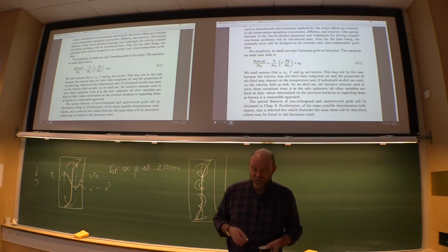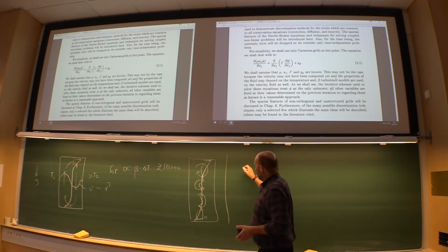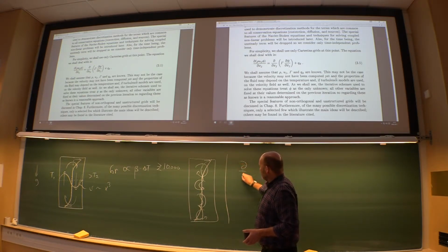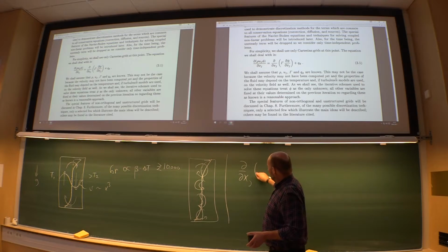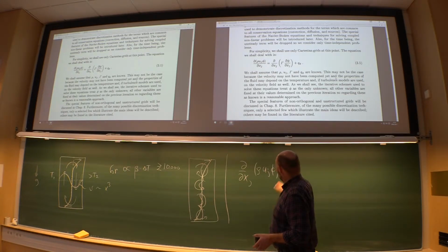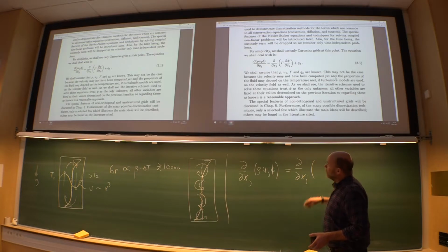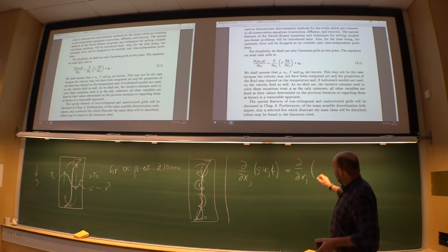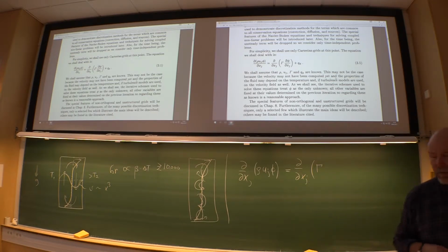Furthermore, you see the cheat there already. Look at the first term. It's written on this conservative form. You have the derivative in front, d/dxj, and then you have rho uj times phi, like that. And then on the other side, you have the x derivative in the j direction of gamma, here being actually a diffusion coefficient.